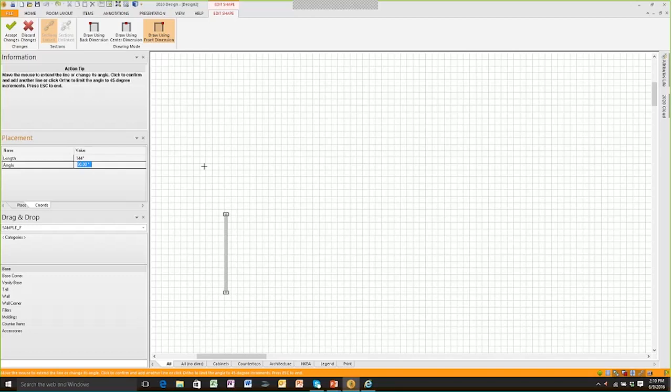But let's say that you typed in 144, you hit enter, there's your wall. If you start to move, you'll see this starts to draw the next wall. If I make the next wall 258, enter. There's my wall. If I point up, my next wall will go up. Let's say that that's 65 inches. If I point it on an angle, it'll be on an angle. I'm going to type it again, 65 inches. You'll notice a little pattern here. I use the mouse to determine the direction. I use the keyboard to determine the length, 65. Tab down, 65. I now have a bay window section.